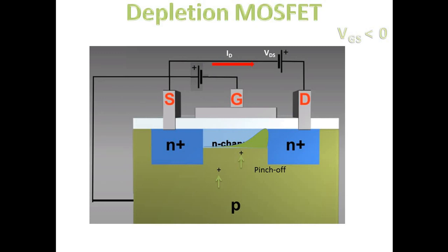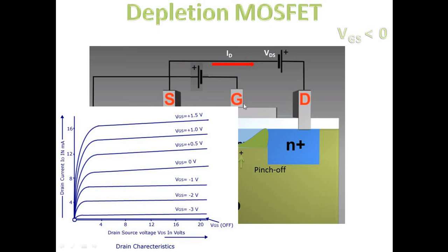Okay. So if I add this portion also in my graph, then what I get is the VGS equal to 0 graph sitting in between. On top we had these plus VGS graphs. Below this particular VGS equal to 0 graph, now we have these curves where VGS equal to -1 volt, -2 volt, -3 volt and so on.